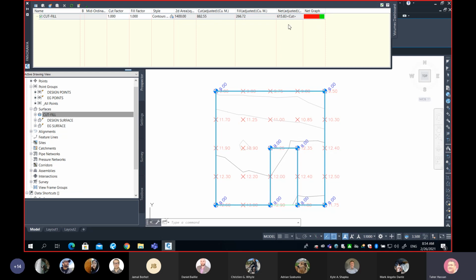What should this diagram look like if I don't want to import or export any soil from the site? Should it be half and half? It should be 50%. And by the way, you can do that here. Maybe you can do a couple of trials until you balance your cut and fill. So this kind of leveling or grade will give you a balance between cut and fill.